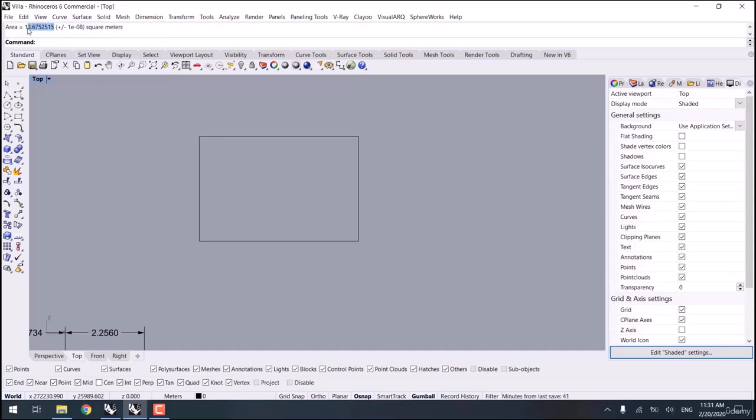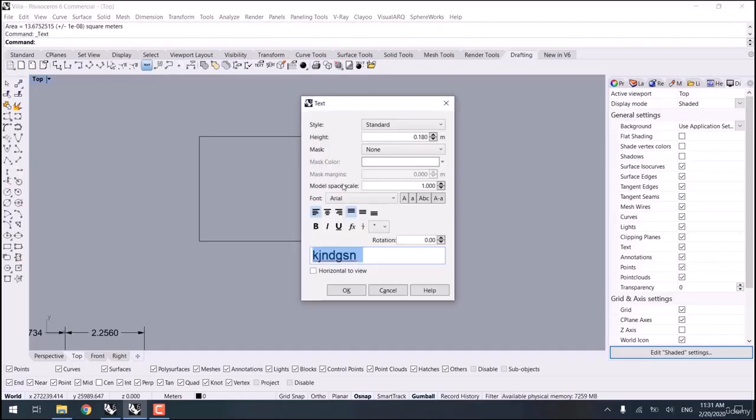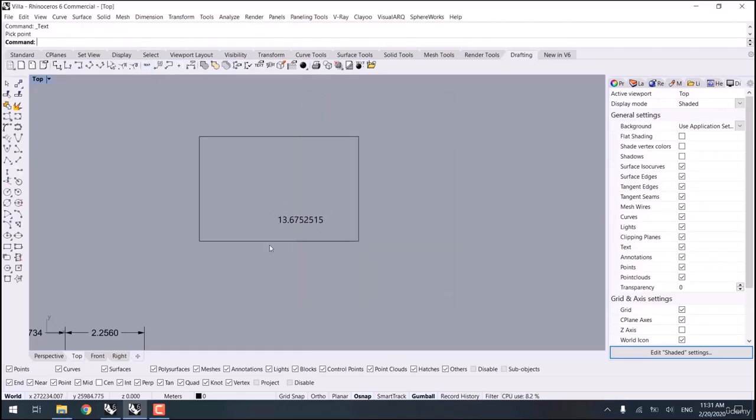Here we are given the area value. I create a copy, and then after copying the value, I add it as a text. Following that, if I maximize the size to modify the area, the text of the area is not changing, is not being updated, since it's not parametric.